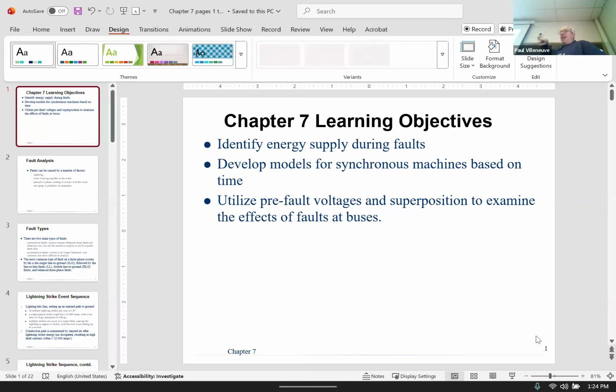The downside is that when you have a trip and reclose operation, you may take 1,000 homes out of service where you could have had maybe 10. So there's more annoyance factor, right, when you have those 1,000 houses versus 10. So it's a balance thing. Do you fuse save and take out 1,000 customers for maybe 5 seconds, because then the lights flicker, that's not too bad? Or do you let the fuse take it out and those customers may be out of power for days?